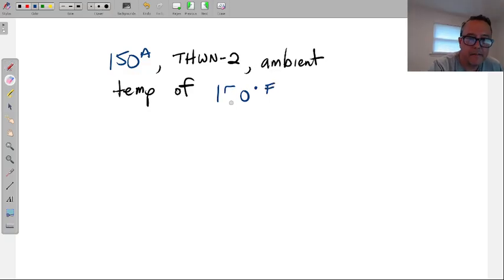And here's the thing. When you get to these high temperatures, it's not as easy, I should say. You can always do the multiplying that I just showed you. But it's not as easy to just go to the table with the wire amperage and go, all right, what's the closest wire to 150? A little bit above. And then start running it through the correction factor, because it takes time to eventually multiply out to the right number, like you saw us do right now.